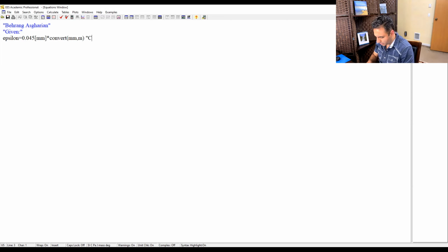And I'm going to just write a note here because this is commercial steel. And if it is commercial steel, your question is, okay, where do I get that information? Go to the Moody chart. Open the Moody chart or the tables in a fluid mechanics book. They give you the value of epsilon for it. And then you have your answer right there.